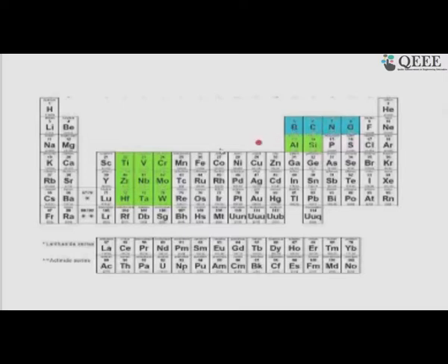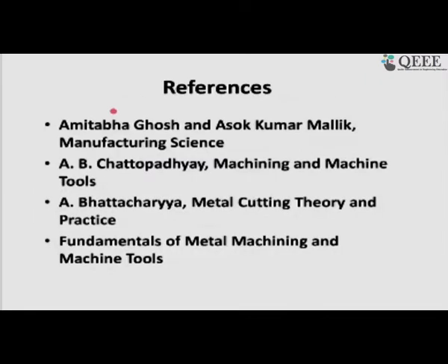It means you have titanium carbide, titanium nitride, titanium oxide. So, metal and non-metal make one composition, and that becomes one of the refractory materials which can give you that hardness or anti-welding property or very, very high chemical stability. So, from this, with the right combination, you can get a cutting tool which can give you that kind of leverage against the wear. Okay, friend, with that we have come almost to the conclusion.